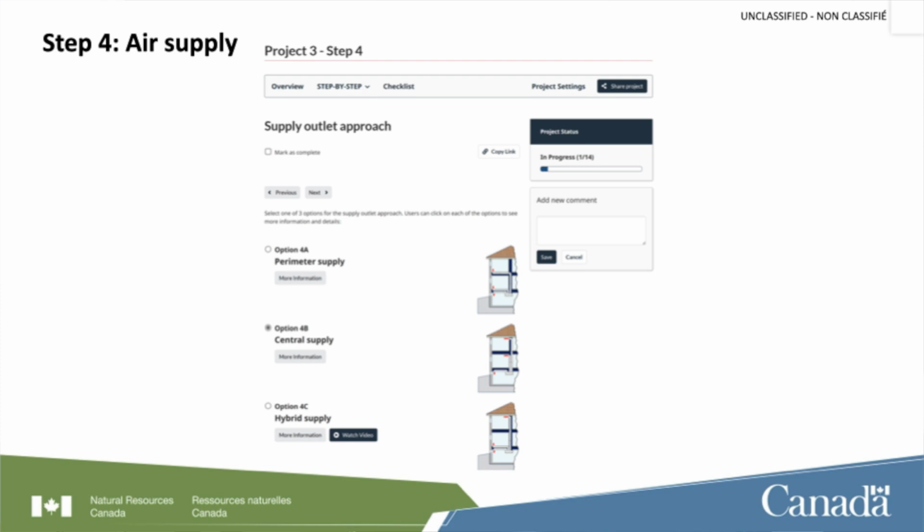But there are other delivery systems that allow us to run a central supply, run a high wall delivery system. The great thing about a high wall delivery system is we never have to worry about somebody putting a piece of furniture over the vent, or the return air, either one. For a builder, you can design with impunity. You don't need to worry about where they're going to put their bed. We don't care. You can put your bed anywhere you want because the supply is 6 feet up in the air.